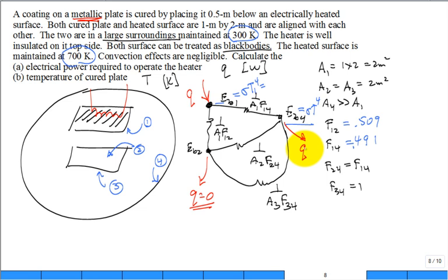So what do I need to do? I just have a resistor network. I just have to think back to electric circuits. And with electric circuits, I need to collapse this into an equivalent network. These two resistors, do it in steps. Going from this node to that node, how would I combine them into a resistor? They're parallel. And then once I have this one, how do I combine this one with that equivalent? Series. And then how do I combine that one with that one? Parallel again. So this is really going to make you good at combining parallel and series and parallel. Combine your resistors. Can you get that equivalent resistance?